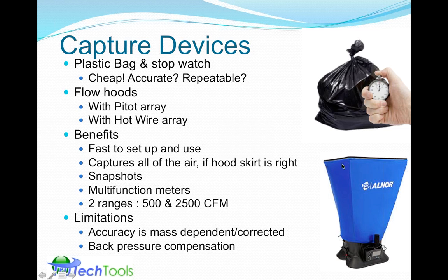Even though it is a very long throw in the skirt, it can still cause back pressure at high enough flow values. There are back pressure compensation flaps that you can introduce. Follow the manufacturer's directions in order to make the device have a better operation when it does introduce back pressure.